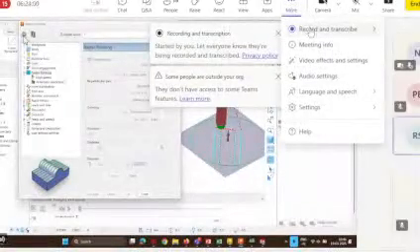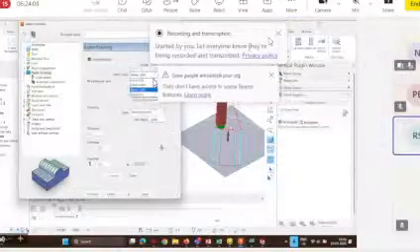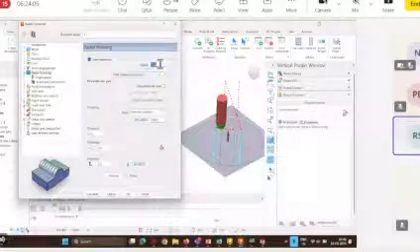Okay. So here you can specify the starting point, angle and all. Then the limit. Then your tool axis you can specify over here. Then you can redistribute the points if it is required. Then the step over you can define over here, whatever you are obtaining from the single bead experiment.